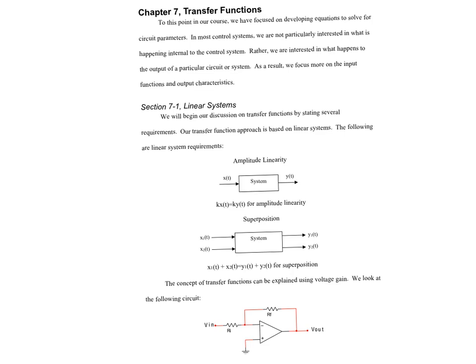But what you can do is take a circuit and break it into smaller circuits, and as long as the interstage loading, which is the loading in between the stages that you develop, is not so significant as to really change the results, you can say, I can just model this little piece, then this little piece, and this little piece, until you model an entire system. Then you can put the whole system together just by tacking those pieces together, and you get a pretty good representation of how your system's going to operate. That's how engineers do a lot of detailed system analysis.